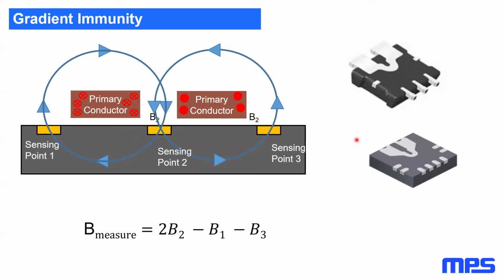This is something that we're starting to integrate into a lot of our current sensors, because if we want to pack, especially, you can imagine in these little QFN packages and this little goofy package that I've got to remember the name of, the idea is we're putting these on PCBs where people are trying to pack 3 phases of current in very, very close together. We want to be able to kill not only the other phases' uniform field, but the gradient field caused by the other phases.